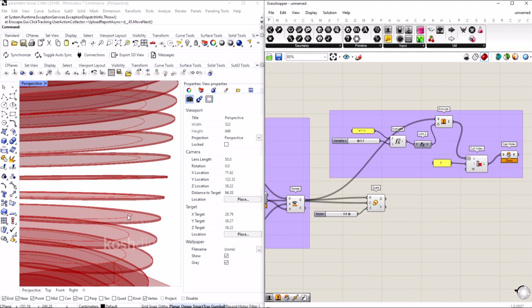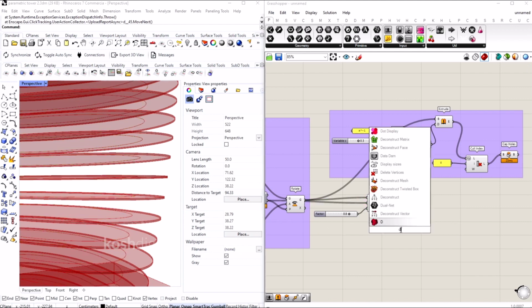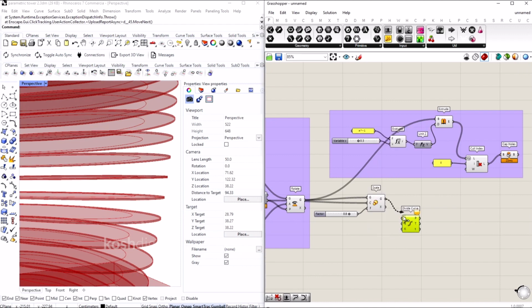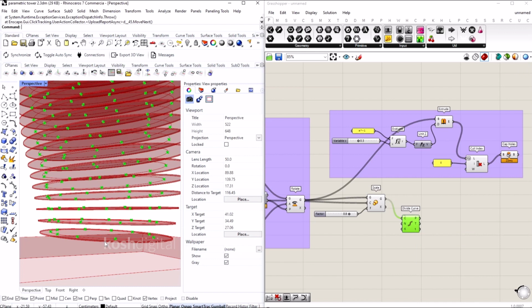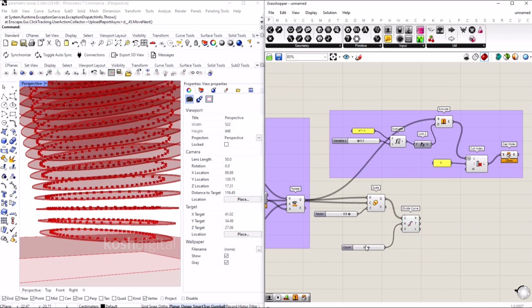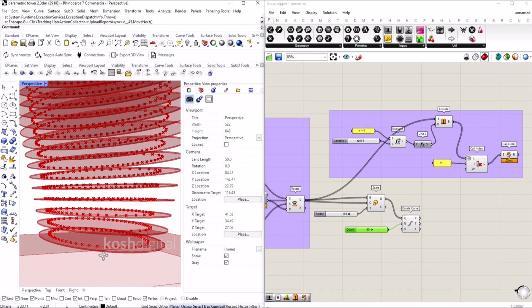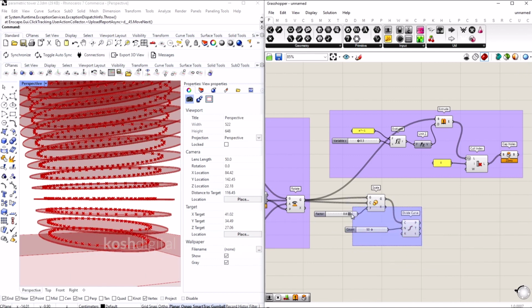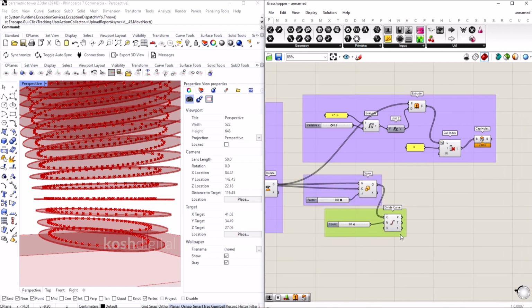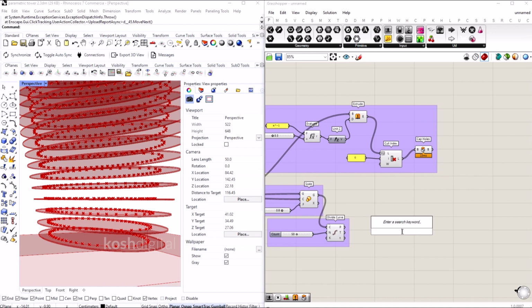Okay, so let's create divisions as well. Create a divide curve. At the moment it is dividing into 10 numbers, I think. Yes, let's create 50 points. Okay, now group this and group this as well. Now convert this as a polyline.